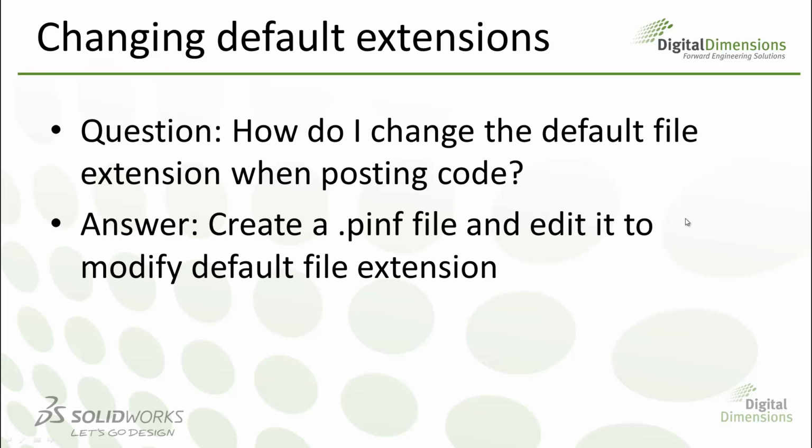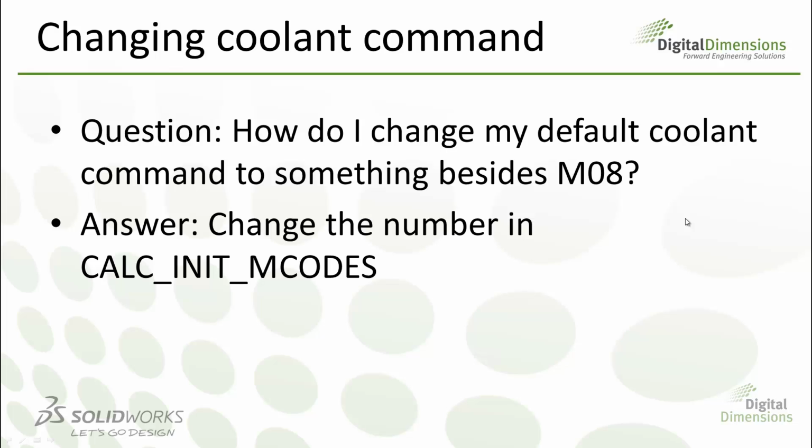So coming back to my PowerPoint, I want to move on to the next question. And so a common question I frequently get is, how do I change the default coolant command? And really this could be any M command or G command in the software, but how do I change it to something besides M08 as an example?